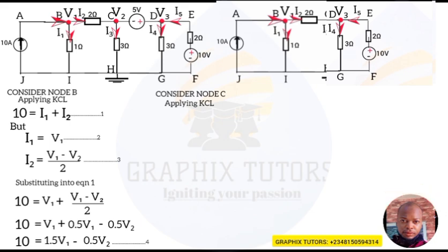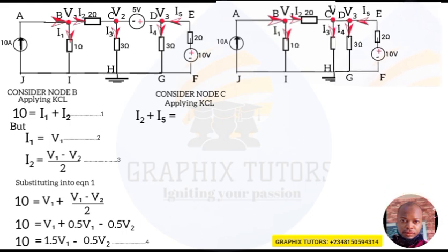So now the I5 that is coming into the super node C here. We make it super because the point C can accommodate the point D. Is that taken? So because I2 is now coming into point C and I5 is coming to point C, we will now say the current entering is I2 plus I5 equals the current leaving. If you look at it now, once you bring node D to node C, 2 currents will be coming down. I3 and I4 will be coming down, right?